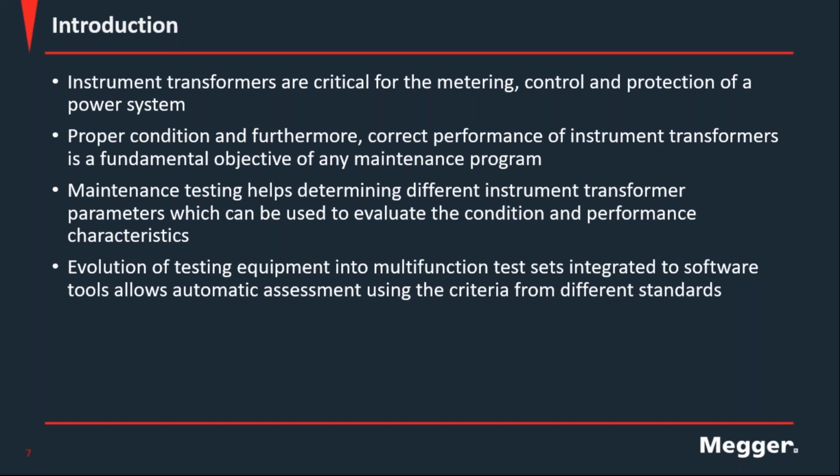This assessment needs, as I was mentioning, results from all the testing, but then it needs some calculations. And these assessments were not common when you tested instrument transformers, because performing that assessment required calculations that were not easy in the field, or you didn't have all the test results because the instrumentation out there was not at the level to get all the results and all the accuracy and be capable of performing everything.